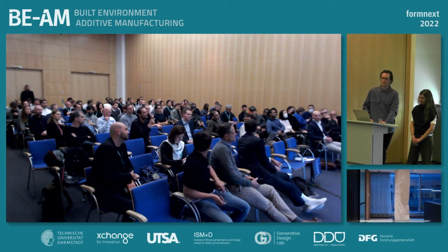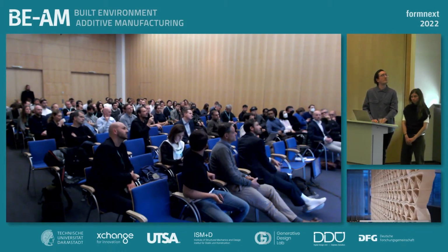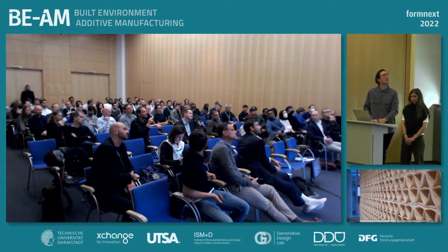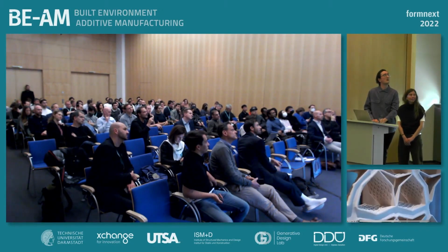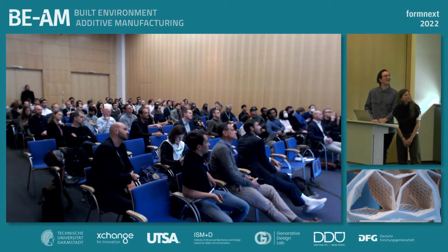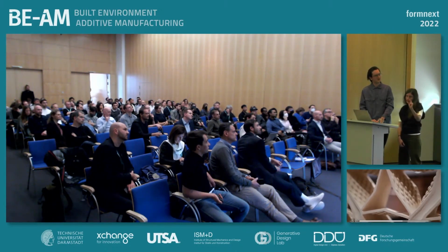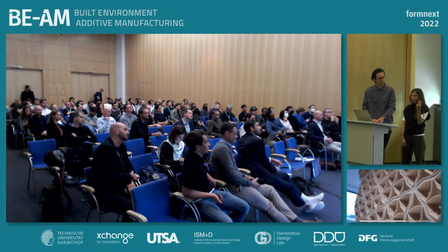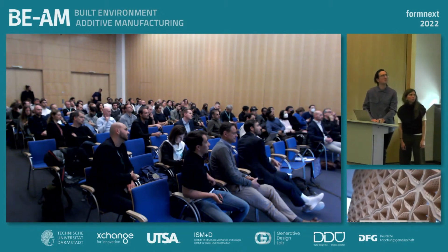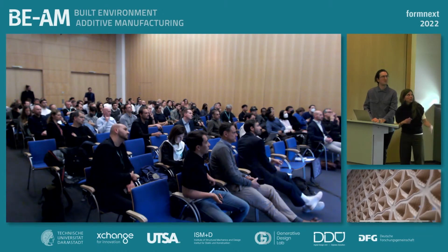Thank you. Just a small question about the wall. How difficult was it to work with differences in tolerance on blocks? Quite difficult. There's a lot of tolerance you can see embedded in the joints. The joints are quite large compared to a traditional bonded masonry system, so we had to build that into the tolerances of the whole thing.